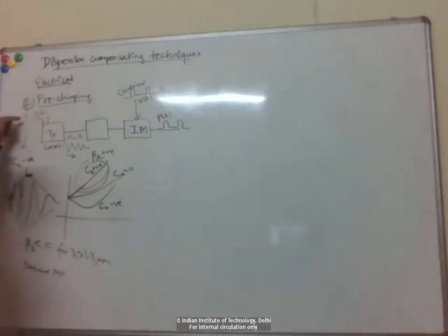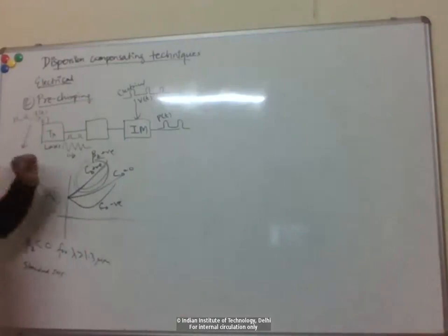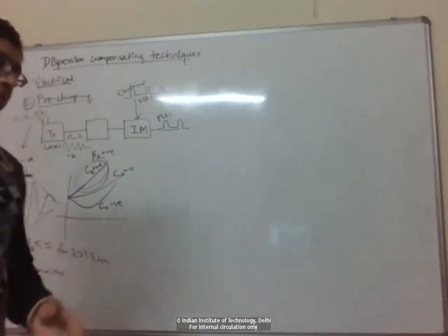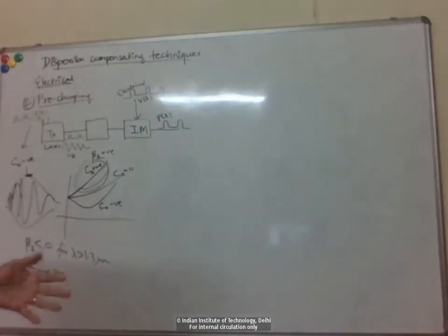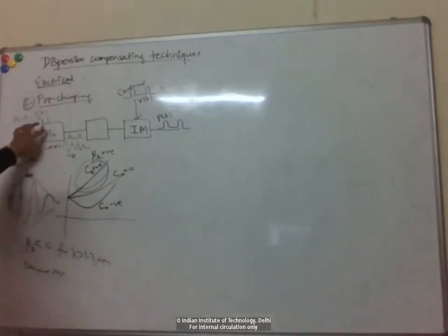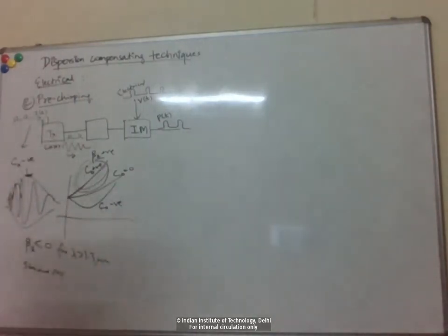That's one reason why we don't use directly modulated semiconductor lasers nowadays. Another reason is that the bandwidth you can get with direct current modulation is limited to maybe 1 Gbps or maximum like 5 Gbps. Going beyond that, just from the RC time constants and the carrier dynamics in the laser, you can't go faster. Nowadays we go to 40 gigabit per second, 50 gigabit per second routinely.